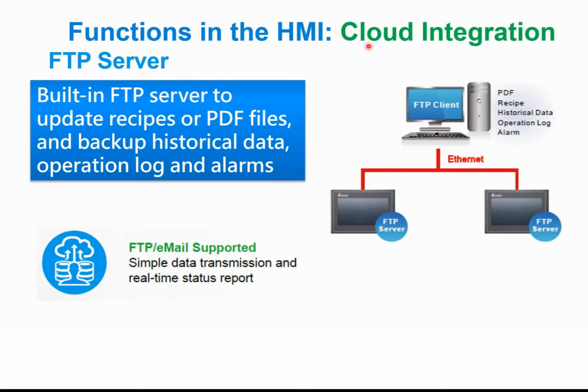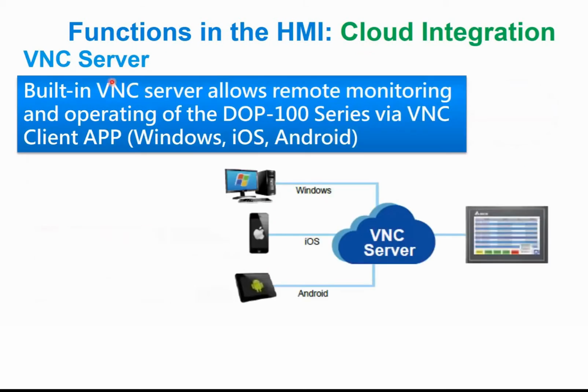We also have another cloud function called the VNC server. This VNC server gives you access to remotely control the HMI. We have different VNC client apps or viewers for Windows. If you install a VNC viewer on your Windows desktop and log into this HMI, you have all the screens of the HMI right away on your PC.